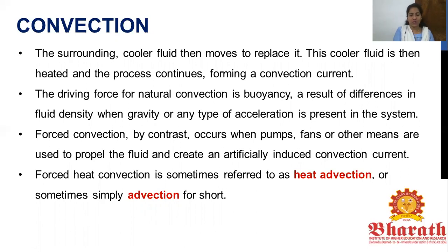We have already seen a few topics, and at later dates we'll be talking about how the courtyard effect and the stack effect work, which is based on this concept of convective-driven patterns. In this, the driving force for natural convection is buoyancy, a result of differences in fluid density when gravity or any type of acceleration is present in the system. Forced convection, by contrast, occurs when pumps, fans or other means are used to propel the fluid and create an artificially induced convection current. Forced heat convection is sometimes referred to as heat advection, or simply advection for short.